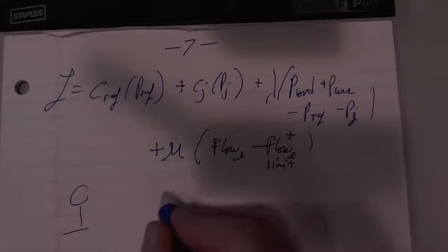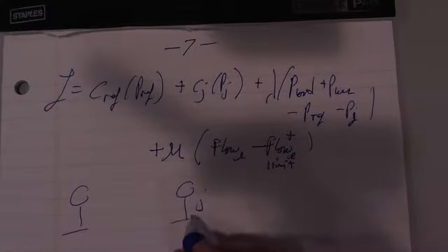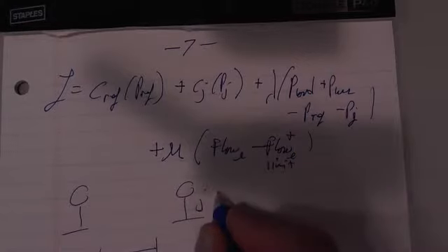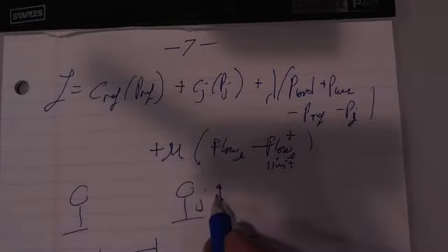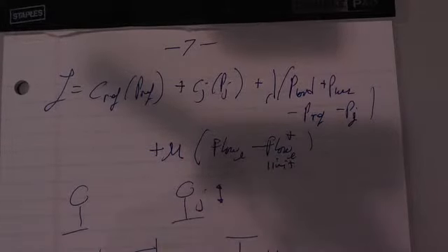Here's this system again. Here's J, and here's our line. We have to know how much does this have to go up or down in order to change the flow on this to compensate for the extra plus 1 megawatt of load over here. This one is going to compensate to force this back. Well, this generator doesn't have a 1-to-1 relationship unless the system is very simple.